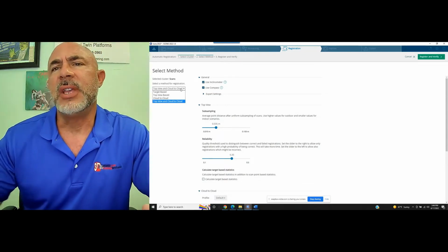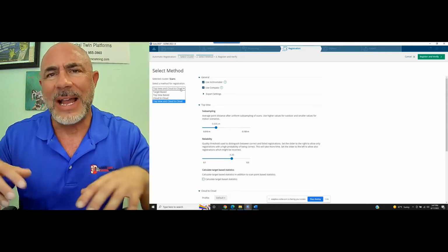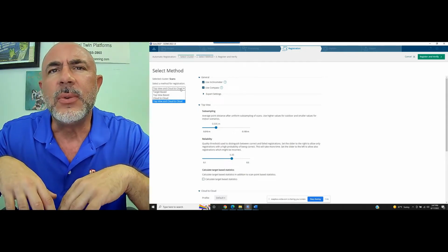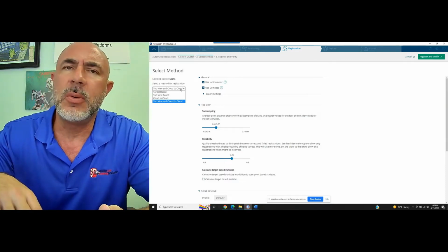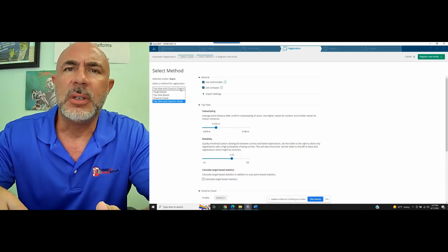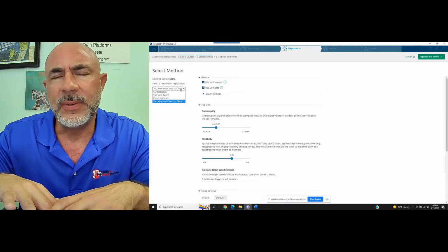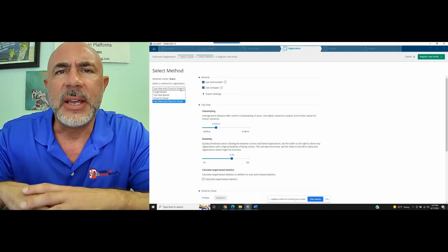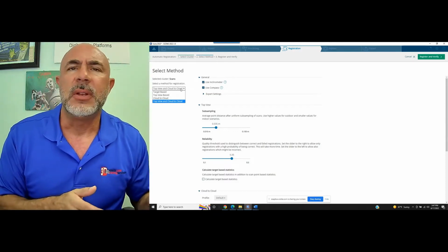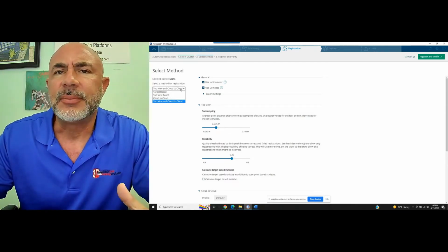So in other words, they're going to take scan 1 and scan 2. It's going to do a top view first, meaning it's going to look down onto the scans and rotate them next to each other, looking for common corners, whether it's equipment corners, building corners, interior, it might be furniture, that might be other equipment, but it's going to rotate them until, like puzzle pieces, they will fit together. They'll just lock them together that way. Once they do that with 1 and 2, then 3 and 4, and 4 and 5, and so on. That will then roughly put the scans together.